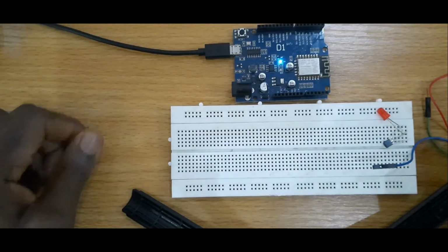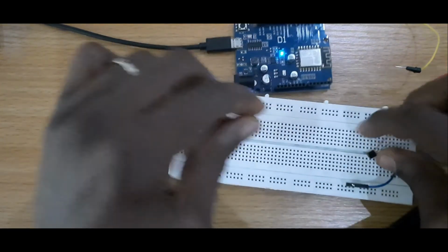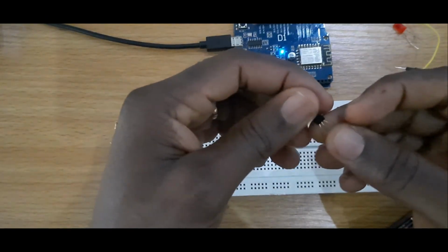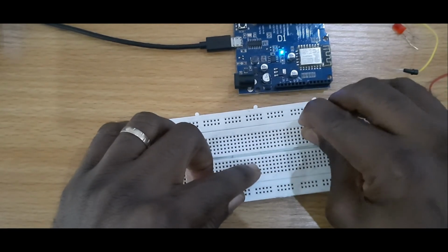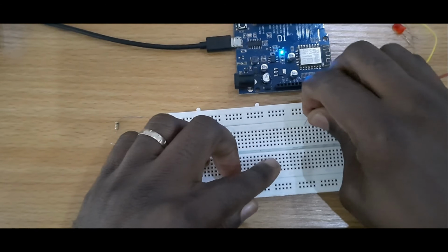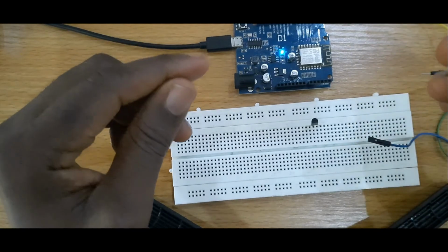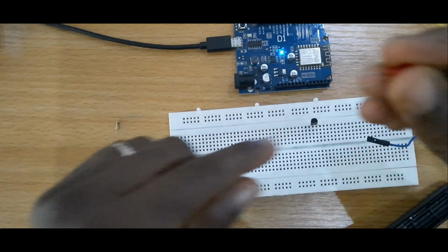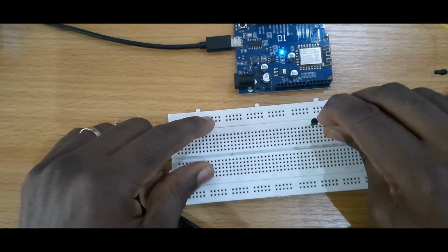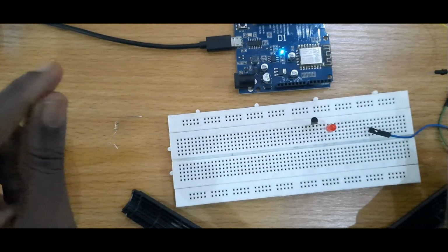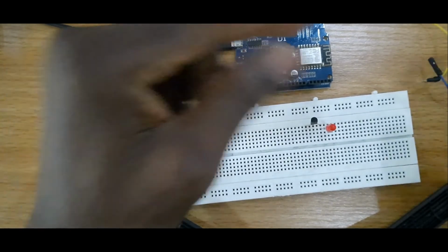First, I'd like to connect my ground. First, let me just put the transistor so you see the proper placement of the transistor. You have the flat side facing you, so you know that the far right is your emitter. That's the part that goes to your load. But I like my load to have the positive. The longest leg of the LED is the positive, so I'm going to connect that to the positive. As usual, the other end should have the negative. I'll use the green for my negative.